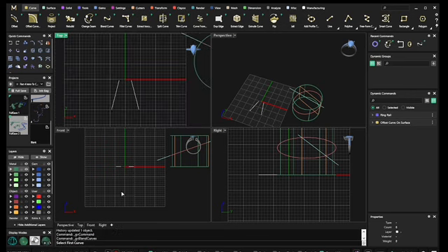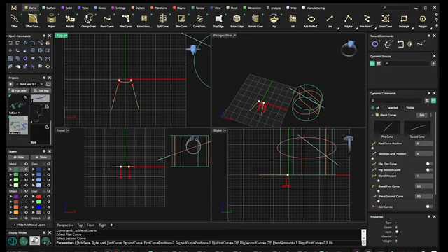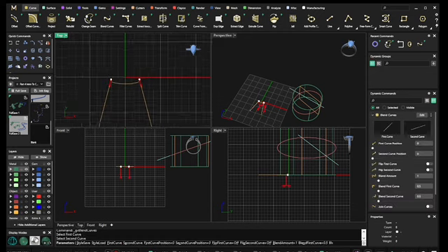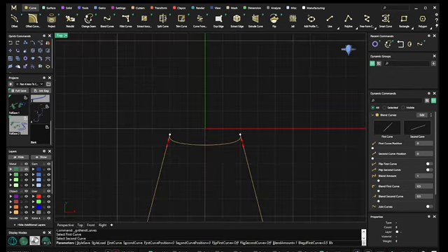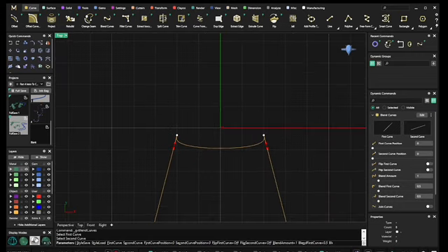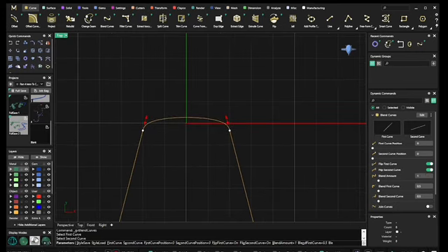Click on blend curve and let's see, select first curve. There we go. Select second curve. All right. Now that looks really wild. So I'm going to go over to my dynamic command box. All right, flip curve. So right now that curve is going inward and I want it to go outward. Flip and flip. Now it wants me to toggle if I want to blend it, and it does give me the millimeter size, so I literally could type in a certain size.